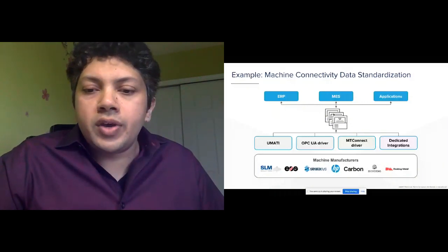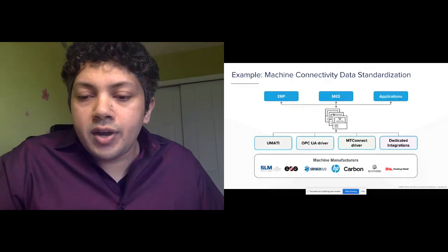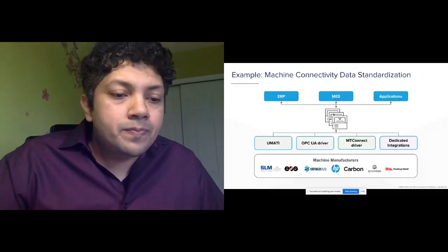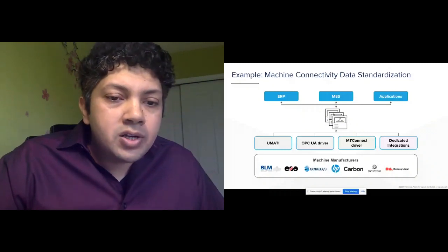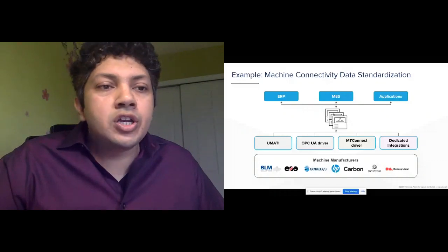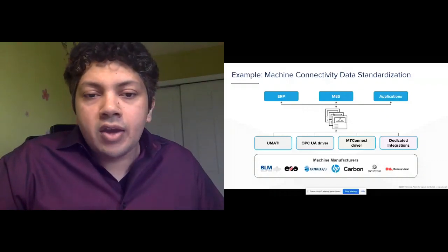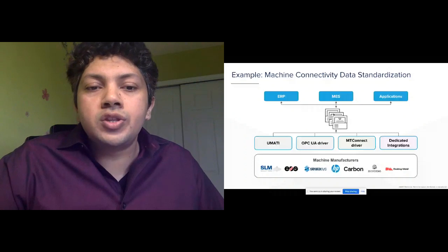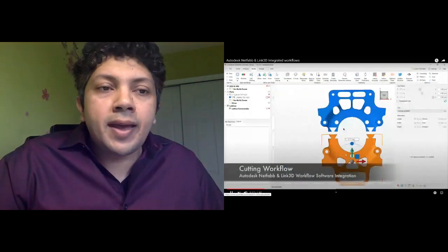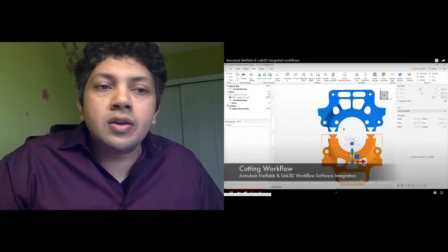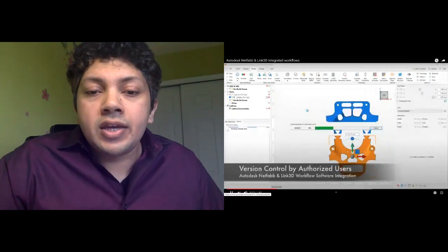I'm going to very quickly go into a small demo. So here is a Link3D dashboard where you can see the order. The order has these parts here which can be automatically exported into NetFab software. And on the NetFab software, we can show that the part can have several operations performed, like cutting, mirroring, inverting, file repair, and so on. And it is saved back.